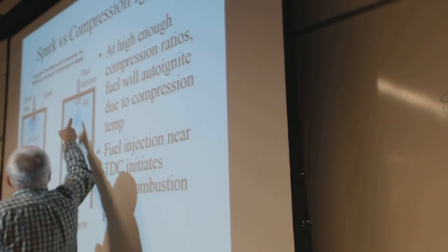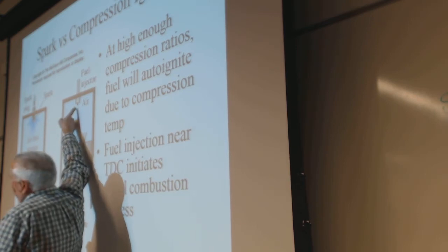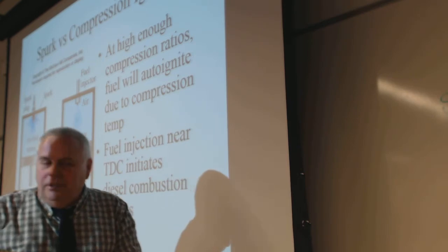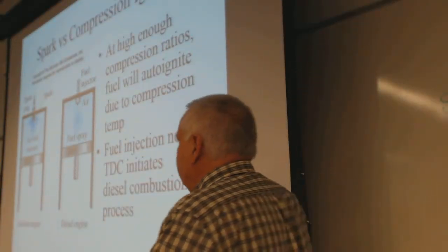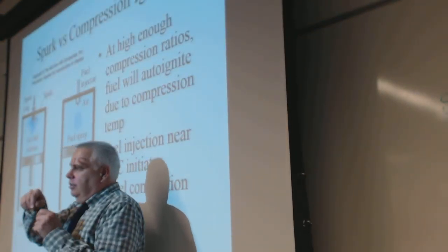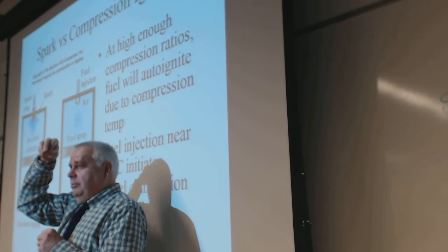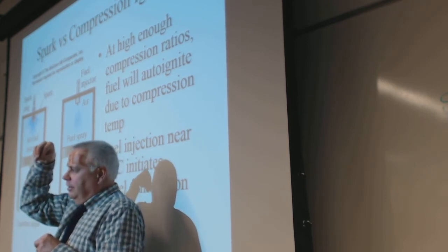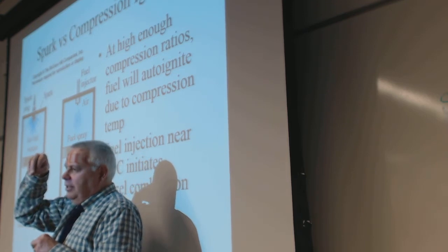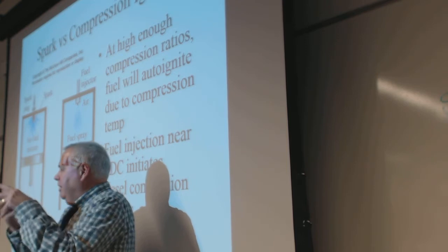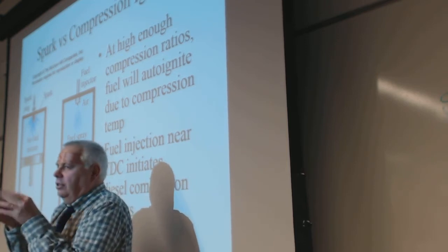And so with the diesel, instead of setting off a spark, they have a timed, direct injection of fuel. Diesel oil is basically crummy kerosene. So you spray kerosene in there, and as you spray it in, it starts to burn. Actually, it comes in relatively cold. I mean, it's probably not cold, but it's not burning. It comes in, there's a little bit of a delay, and while it's warming up, it's mixing with air, and when it finally gets hot enough, it starts to go.